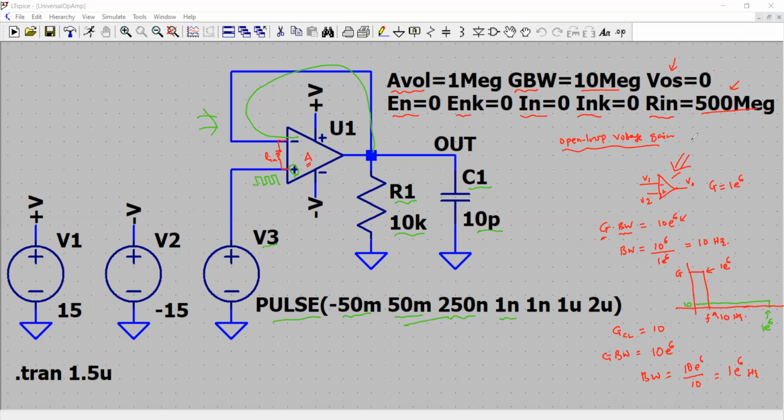So anyways, I have explained the concept of gain bandwidth product, which is always constant. Now, your gain is 1, for example, because your output is equal to input based on the theory. If the gain is very, very high, open loop gain of the op amp, let's say 10 to the power 6, it means your difference of the inputs is approximately 0. So you have a gain, which is the ratio of output by VID, the differential input. If gain is very high, VID, which is the difference between V1 minus V2, is equal to 0, right? If this difference is very, very less. Ideally, if it is infinite, then it has to be 0,